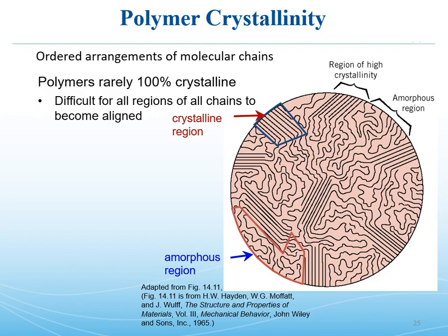So quite often one chain will go in, fold back and forth in one of those crystalline lamellae areas, exit it, and then incorporate into another one. So the lamellae crystals may be literally continuously linked by a covalent bond, but that covalently bonded chain that is present in both may travel quite a long way and entangle in the amorphous region en route.